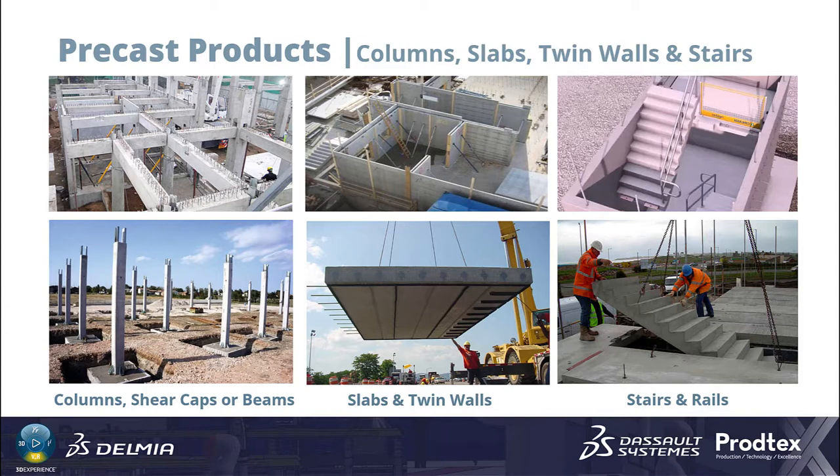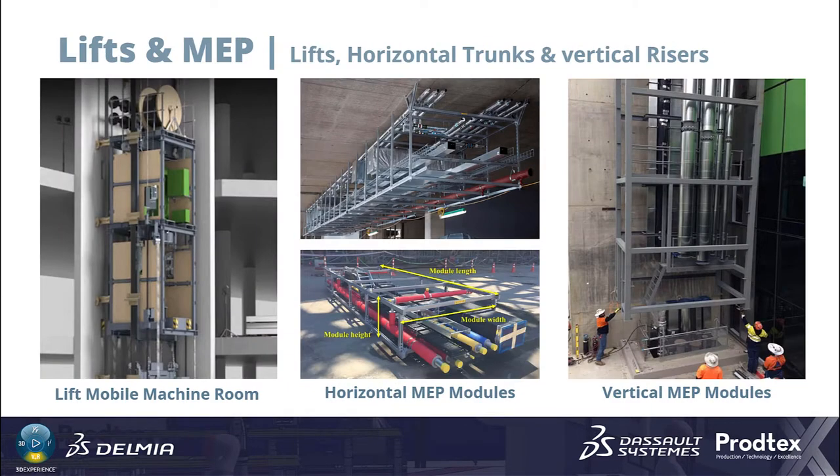And finally, on the right, you see the stairs as they're dropped in. Now, these stairs could contain the rails and guards areas, but they might be just stairs by themselves. The reason you want to try to put these in as quickly as possible is this is a convenient way for workers to take their tools and get access to the floors where they're working without having to use man lifts or other things on the side of the building like scaffolding. Reducing man lifts, reducing scaffolding, and reducing formwork is part of the way that we make these products operate more efficiently.